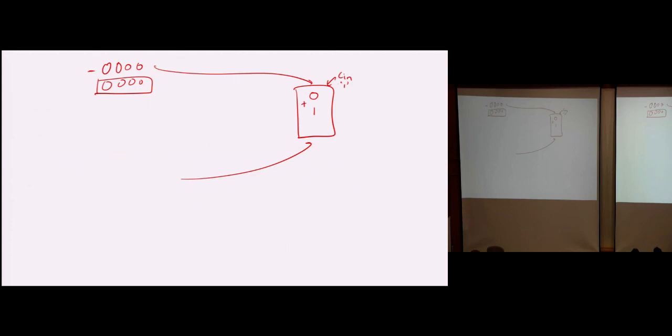How do you calculate this one? Because this is a subtract. So wherever there's a subtract, there is a one carry, because it is 2's complement. 2's complement is like invert plus 1, correct? So this is invert, then I must still have a plus 1. What do we learn about number representation? We learn that 2's complement is original bit flip plus 1. That's what I'm doing. So for the least significant bit, after I flip, I must add 1.